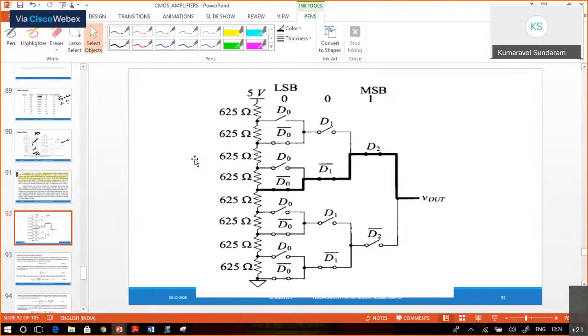But when you come to research, now we should look at the characterization. What contributes to the non-idealities in the resistor string DAC? We have seen INL and DNL. This we should calculate to check whether monotonicity is maintained, that as we increment the digital code, we are able to find the increment in analog output voltage, which we have to see using the DNL characteristic.